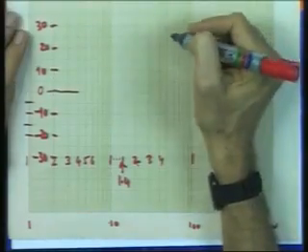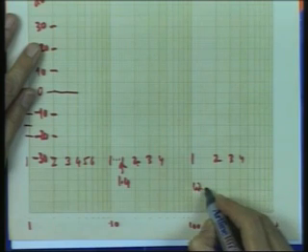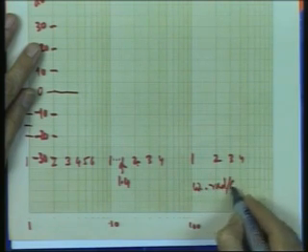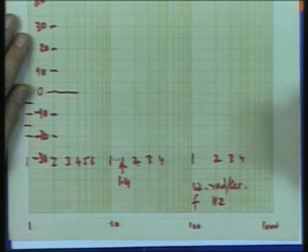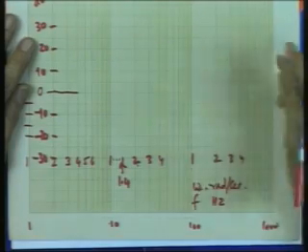It is always better to mark along the two axes your variables or quantities or at least the scale value. So, here it is better to write dB. Of course, we are plotting gain, so we need not write dB gain. On this side you can write omega if you are marking omega, and therefore, omega in rad per second, or frequency if you are marking frequency, then frequency in hertz or cycles per second. So, with this semi-logarithmic paper, then using Bode's approximation, one can get a fairly good idea of how the gain is going to vary with frequency over the range of interest.